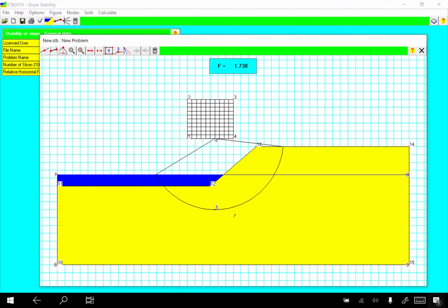But you may observe one thing, that is the most possible center is right on the boundary of this mesh. So that could mean that this point may not be the most possible center. The most possible center may be out of it. So to confirm that, let's enlarge this mesh a little bit. We can also use the drag node function.